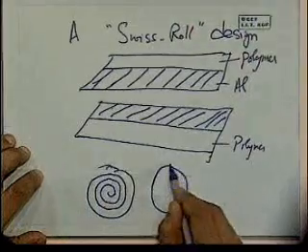Okay? Now on one of these electrodes, or on one of these films, the electrode is on this side, on the other one, the electrode is on this side. So on both sides, I can put a metallic contact and get electrode connections to alternate layers of the film. So it's very much like the ceramic idea here. Instead of it being like a solid stack, because my polymer film is very thin, I can roll it up. So my rolled up, this is the Swiss roll, is now going to be given an end contact.